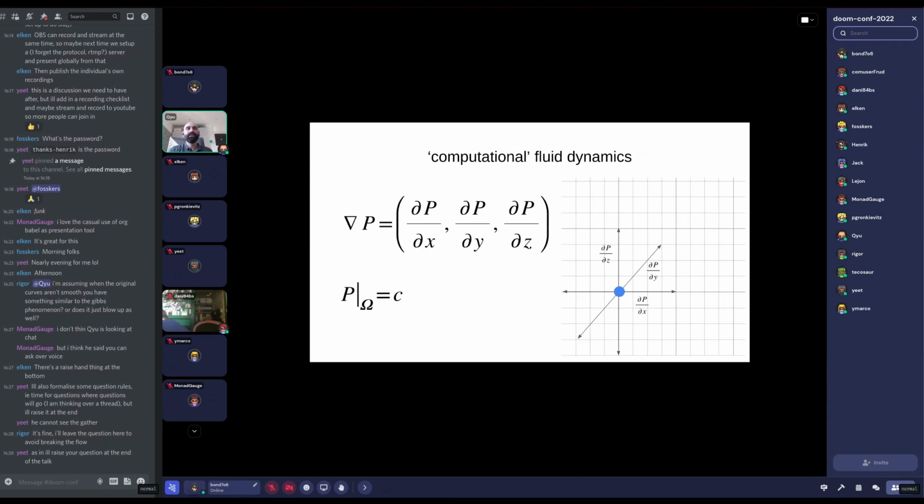Okay, so importantly, when we looked at the pressure gradient, we need to think what a gradient is. We're now in this three-dimensional space, and pressure doesn't change with time. The pressure actually changes with space. And this operator is called the gradient operator, and it takes this scalar value, this p, which is not a vector, and it needs to know how it changes in all these different directions. So the pressure needs to change in the x, y, and z directions differently.